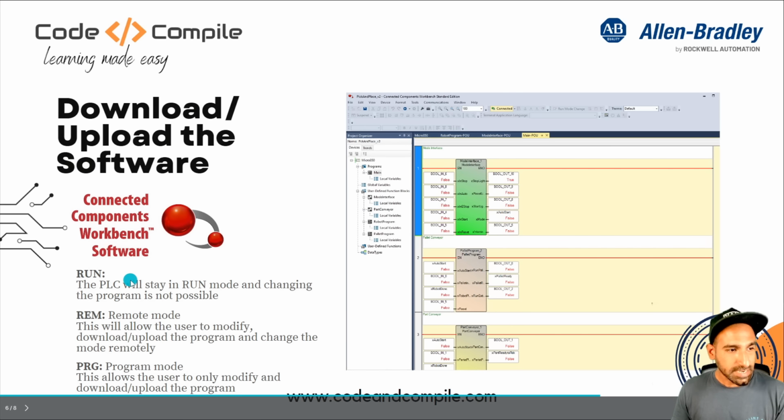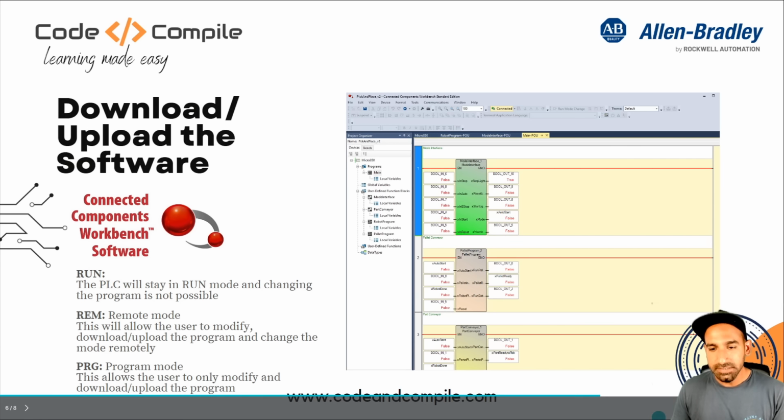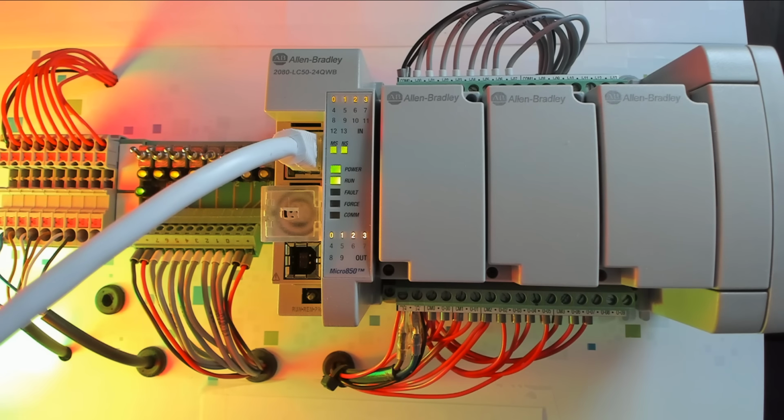One is run status, remote mode, and program mode. It means when the PLC is in run mode, you can't change the program, right? This is a kind of security, and you will see these three modes here on the bottom. If you see here, there is a switch, and here on the left it says run, in the center is remote, on the right side is program.